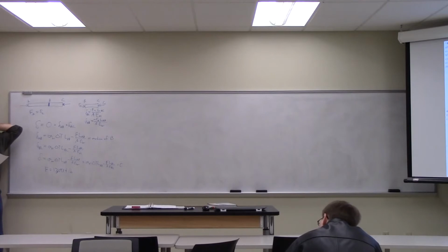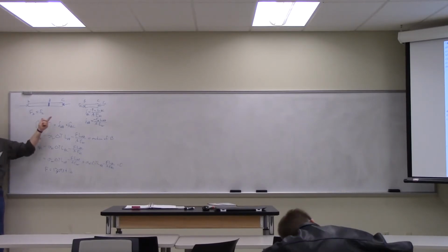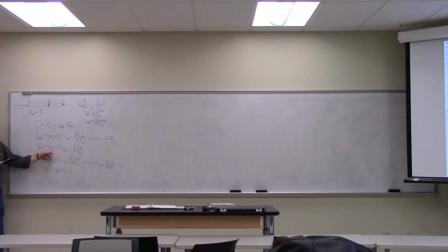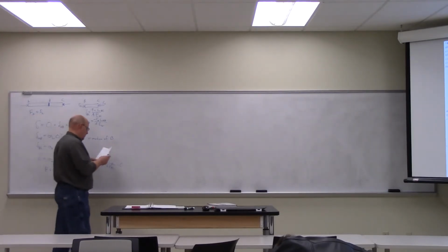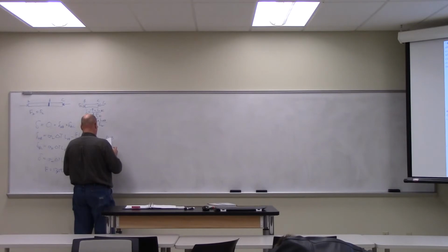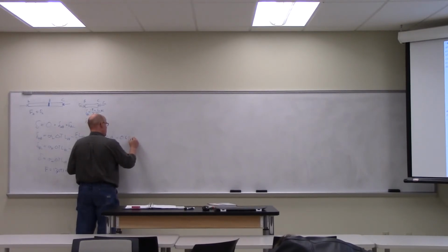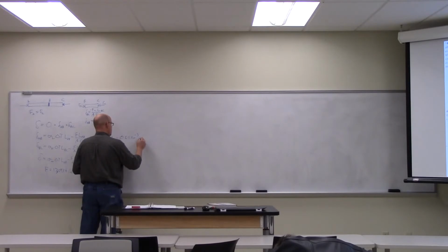Okay. If I plug that into this value down here, I would just get a negative of the same thing. So if you took delta AB minus delta BC, you'd actually end up with 2 times the motion of B, because this one's negative. Okay? So if I plug that number back in, using all the other values that we have, we end up with 0.611 times 10 to the minus 3 inches.